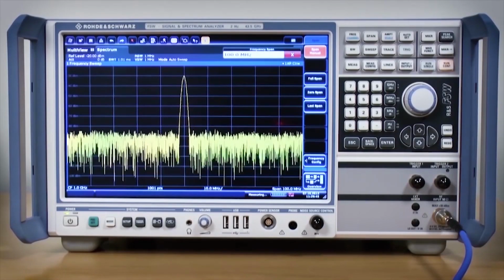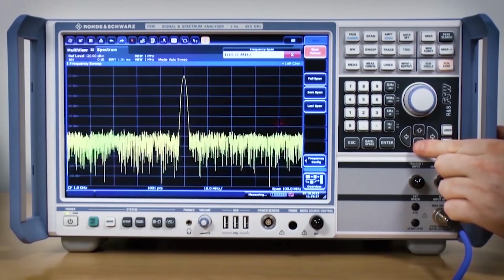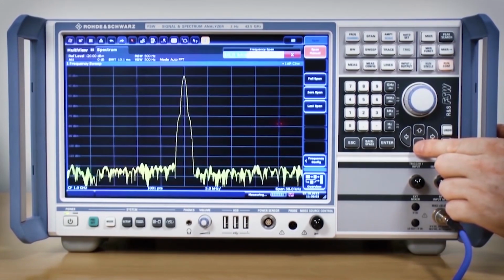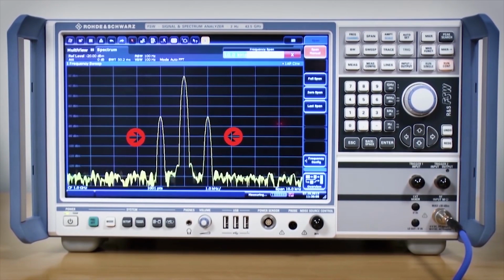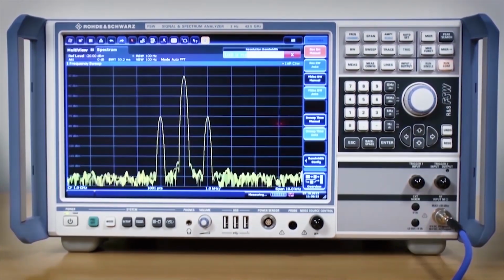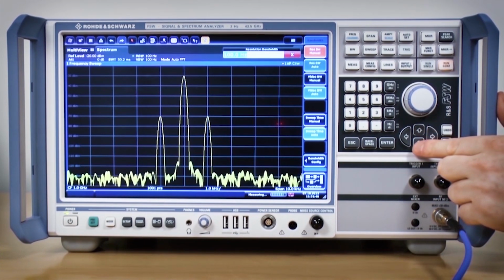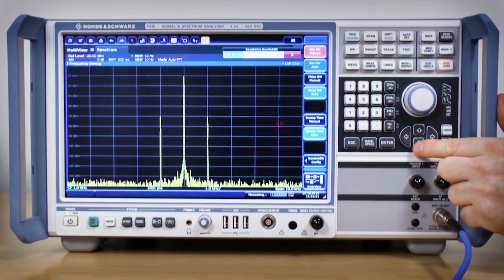Here we see an amplitude modulated signal on the analyzer screen, but to see the sidebands we need to adjust the span. As this is progressively reduced, the spectrum analyzer scans a smaller bandwidth and the sidebands are seen. In reducing the span, the analyzer has two controls linked together. The first and the most obvious is the span, the actual band that is scanned. However, it also reduces the resolution bandwidth. This is the same as the reception bandwidth of a radio. The smaller the resolution bandwidth, the higher the resolution of the scan, and the more detail there is.